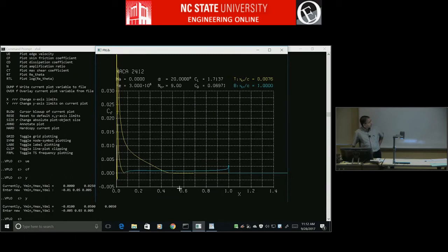So let's take this piece by piece. What do you think is happening here? That's the big turbulent separation on the back part of the airfoil, almost. So you can say, by looking at this, the separation starts at about 45% on the upper surface, and after that it's all separated. CF will be slightly negative or zero.